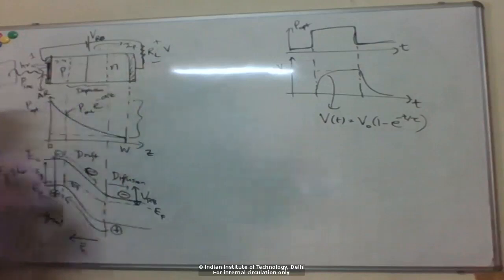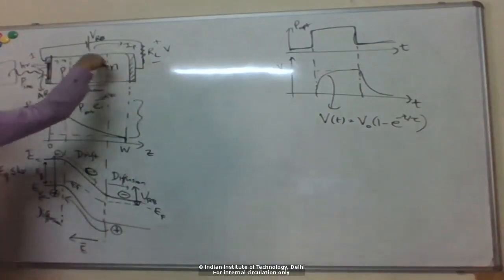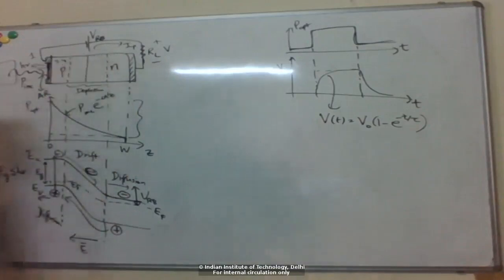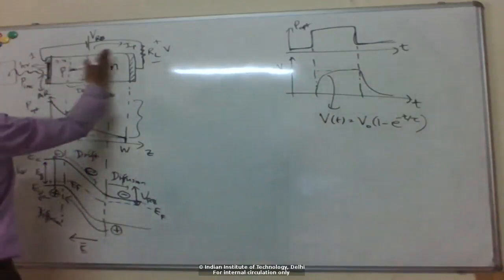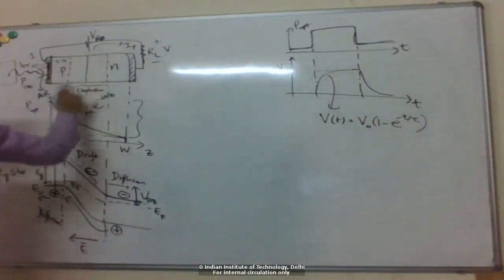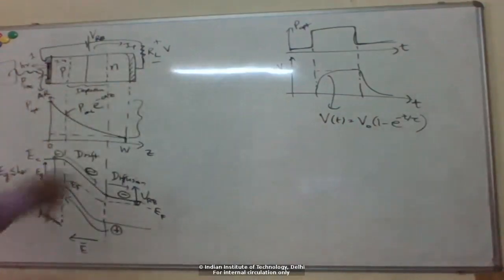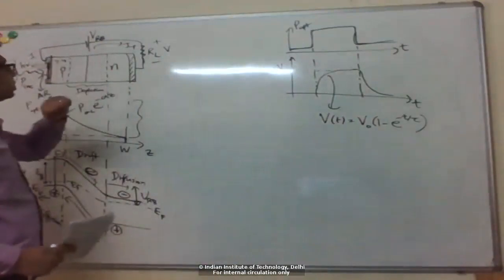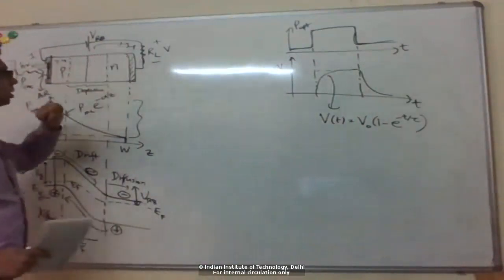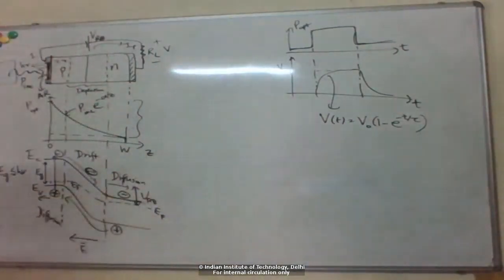Basically, you have a load resistance here already, and you know that there is a capacitance associated with this reverse bias p-n junction, right? So because it looks like almost a parallel plate capacitor with positive and negative charges on two sides of a dielectric, right? So there's a capacitance associated with the device and also a resistance. So there is an RC time constant, right?